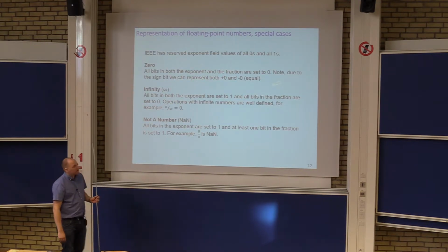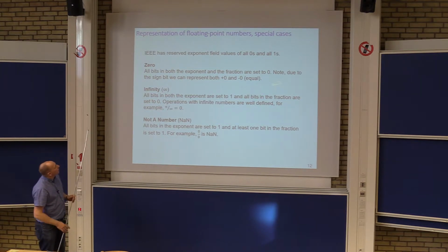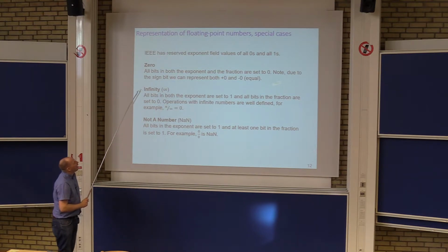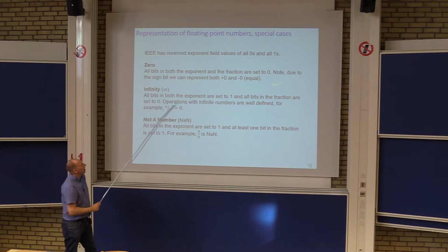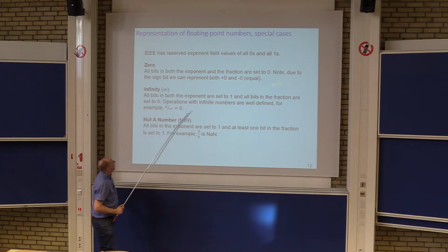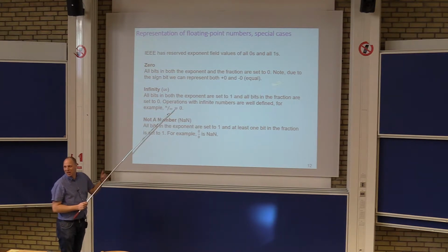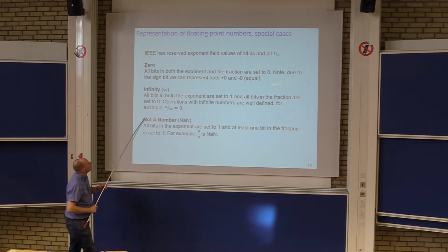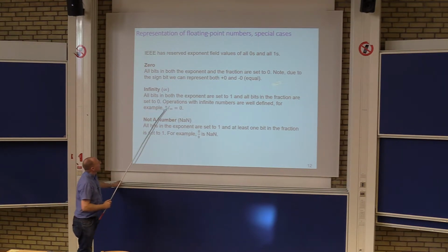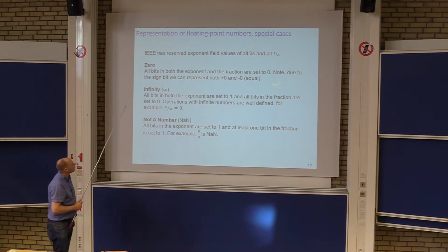There are some special cases. So with floating point numbers, actually we have this drawback here that there are two ways to represent the number 0. So we can have +0 and -0. So of course this is an extra complication that you need to deal with in hardware, but floating point numbers are much more complex in the hardware anyway than integers. But still there is support in the hardware to do these calculations today in most of the processors.